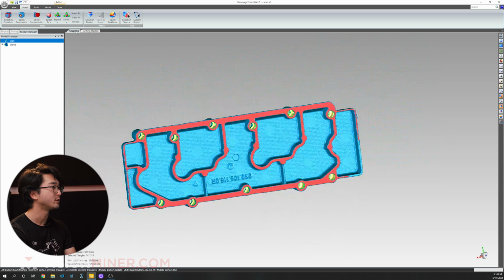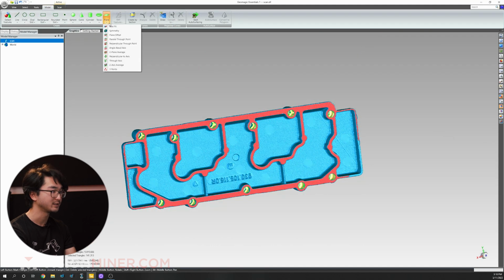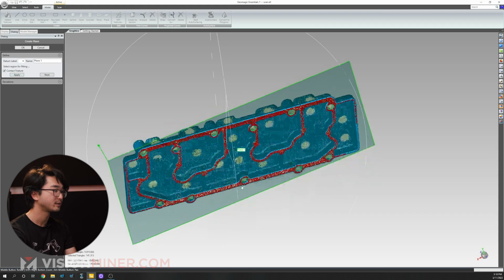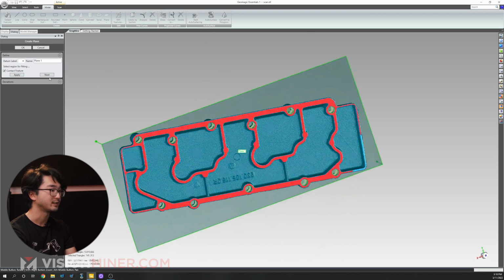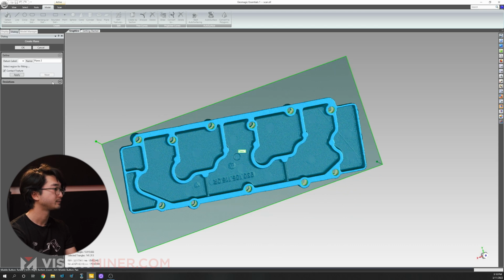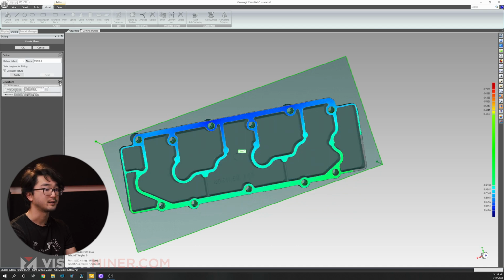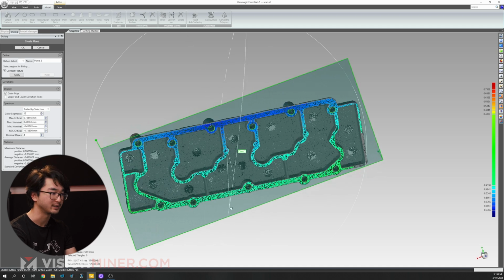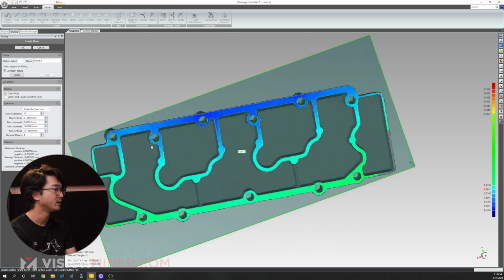And that's going to help me create my best fit plane here, which if I go to the Model tab and I go to Plane, I can click best fit and click apply after clicking contact feature. I'll click next to save that selection. And then I can also click on the deviation drop-down menu here to see how far this plane deviates from the surface. So you can see here, according to this heat map,